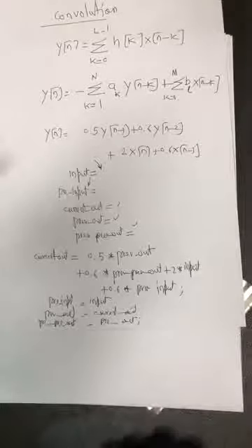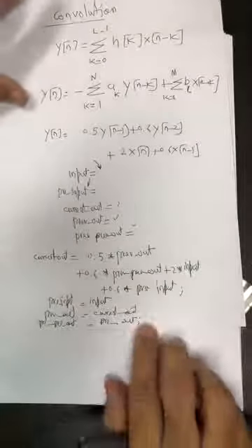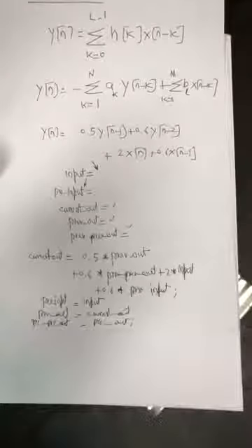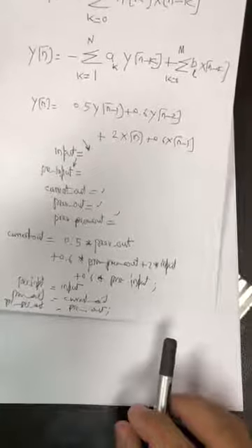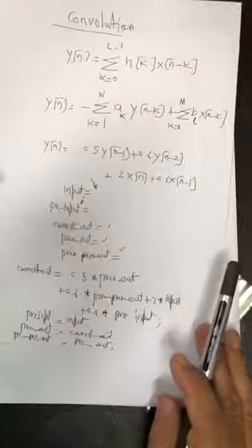He was making a telephone exchange with just the DTMF detection using a difference equation like this. And he almost did something like this, a long piece of code which he wrote, and the exchange could only process like 5 calls, and they wanted to do 64 calls. And then I changed the code, knowing the DSP helped me to optimize it, and the same exchange could do hundreds of calls. So obviously it matters that you know the different ways of implementing a signal processing system.